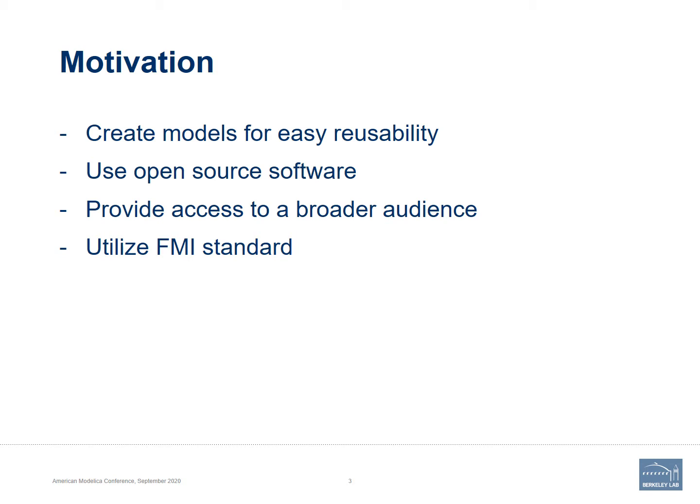And if people are not using Modelica, we also provided all the models as FMUs utilizing the FMI standard. So people can use the blocks in any kind of software which supports the FMI standard too.